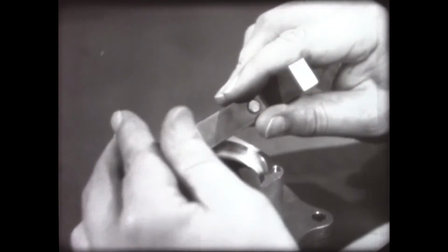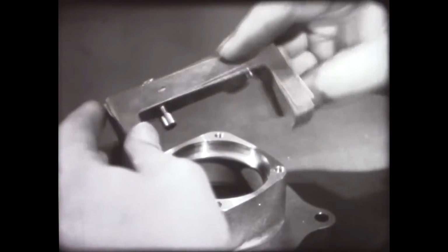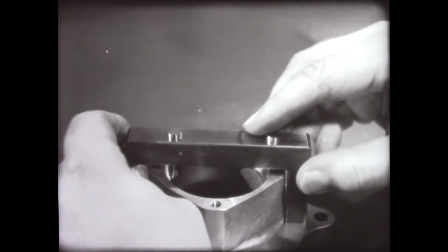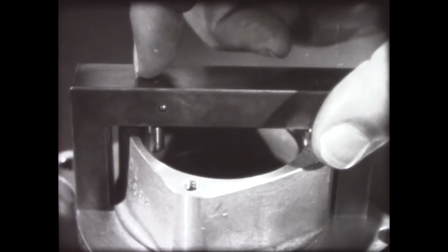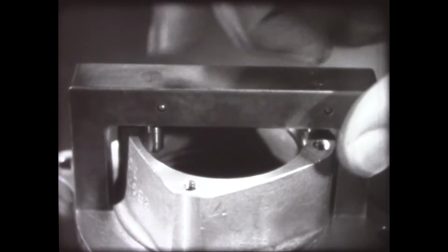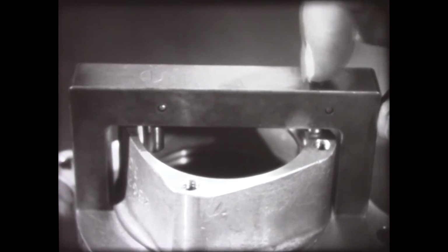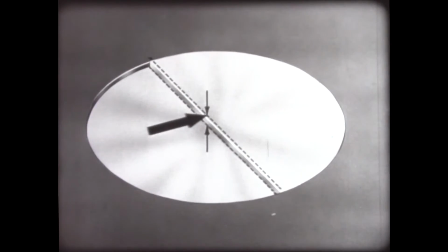Another kind of gauge, usually of special design for each specific job, is the flush pin gauge, widely used for checking depth dimensions. The pins are brought into contact with the location to be gauged. The tops of the pins are cut in steps to the limits allowed. The lower step should be flush with or be below the top surface of the gauge.